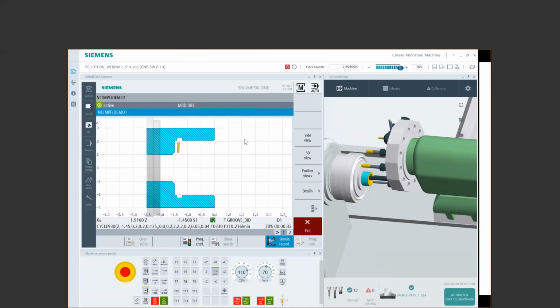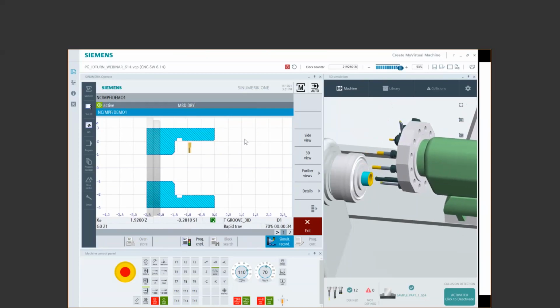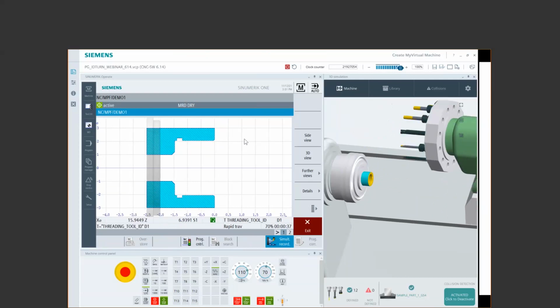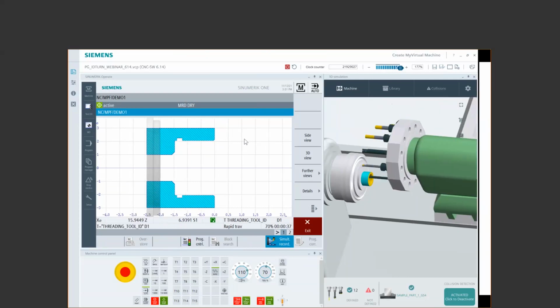She'll take a little finish cut here. There's your finish pass. And now this is my wrap it out to 1 inch away, load the tool, just to make sure that I don't get into a scenario where I clip my part. Now we're doing our single point threading, right? So come on through, depending on how many passes, based on my starting and my chip load and all that good stuff.